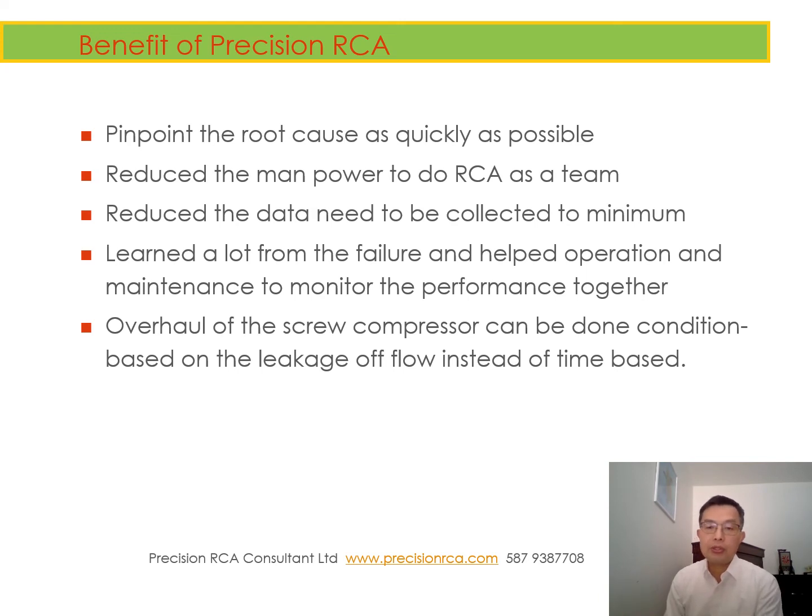Every 2 or 3 years, and at the last stages every 2 months, we needed to do a turnaround overhaul for this screw compressor. Now we are based on the leakage gas flow. Based on this flow amount, we can adjust our overhaul plan. It also reduced a lot of unnecessary mistakes brought by unnecessary overhauls.